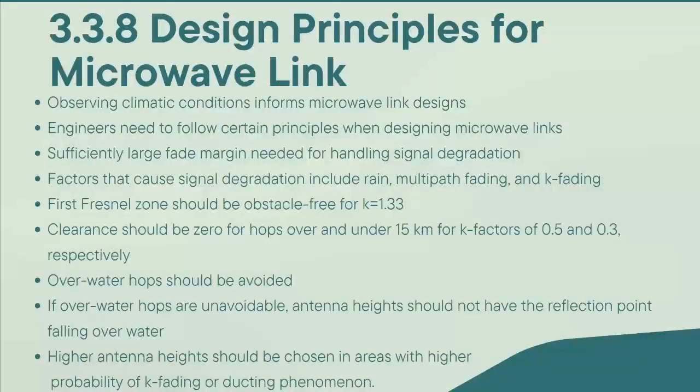Overwater hops should be avoided, but if overwater hops are unavoidable, the antenna height should be chosen so that the reflection point does not fall over water. Also, higher antenna height should be chosen in areas with a higher probability of K fading or ducting phenomenon. So these are the principles for designing the microwave link.